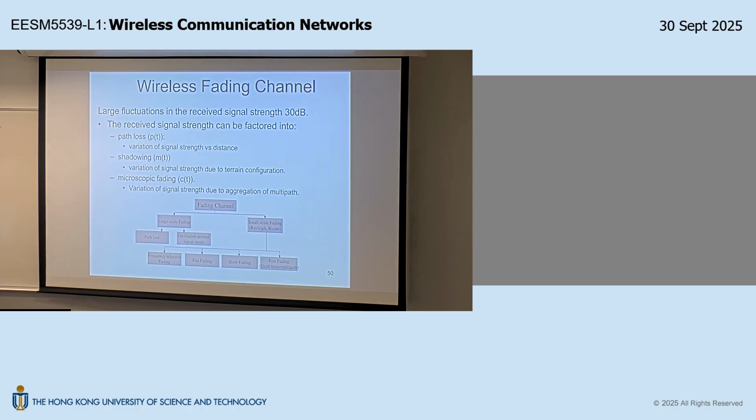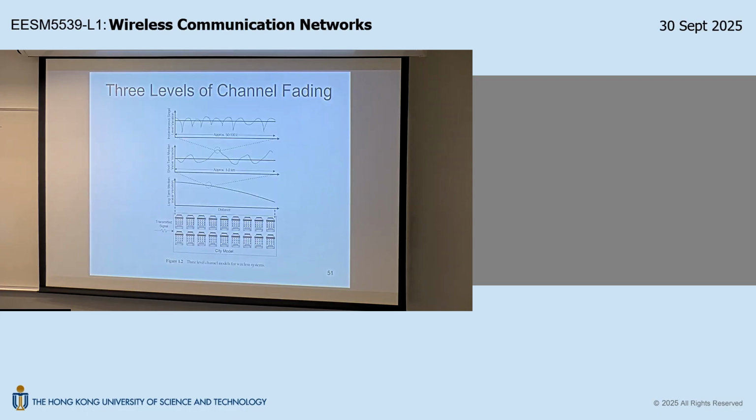Do you need to worry about microscopic fading? No, rarely, because microscopic fading changes on the millisecond order. So that won't affect your so-called link budget analysis. Usually that's not relevant.